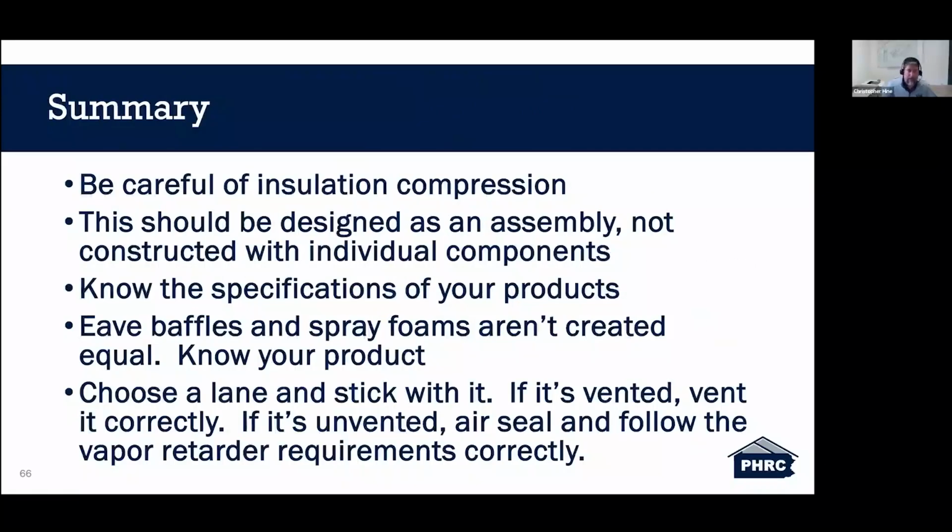So in summary, a couple things that I want to highlight here is be careful of insulation compression, right? Look at that entire assembly. Look at the thickness, the loft of your chosen insulation, and if that is compressed at any point, is that compression at all allowed? And if it's not, you need to take a look at that assembly, and either change your insulation or change your baffle or change your rafter. You know, if you're using a 2x10, maybe you have to go to 2x12 or jump outside of the box and go to an engineered product.